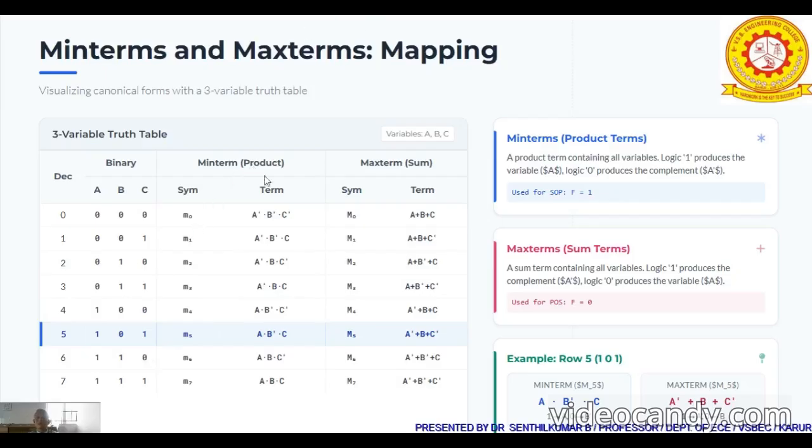So the expected minterms for the corresponding binary numbers are like this. Look at this. In case of minterms, wherever you see 0, it is considered as a bar, because for this term the relevant input is A. Since there is 0, you see A bar.